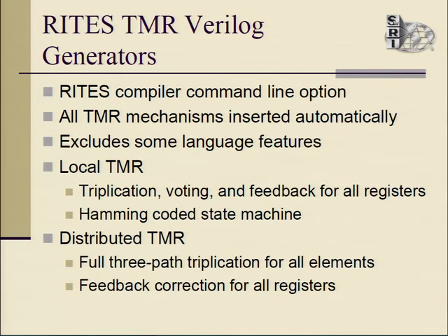So in the RITES Verilog generator, whether or not you want to use TMR, local or distributed, is just a command line option. All of these TMR mechanisms are inserted automatically. So all of the copies of registers, all of the voting and the interconnections, are all automatically generated.